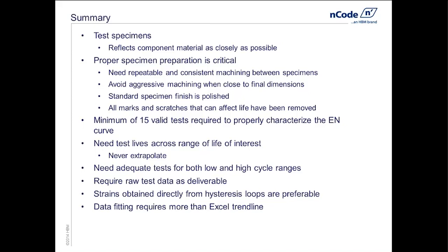But in most cases, they will have captured the hysteresis behavior and measured values for elastic and plastic strain as well, and you want that data. Again, you need to understand the range of the data to know where you can and can't use this curve. Strains obtained directly from the hysteresis loop are preferable.